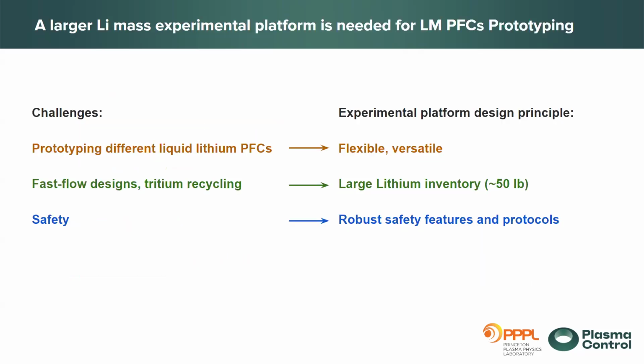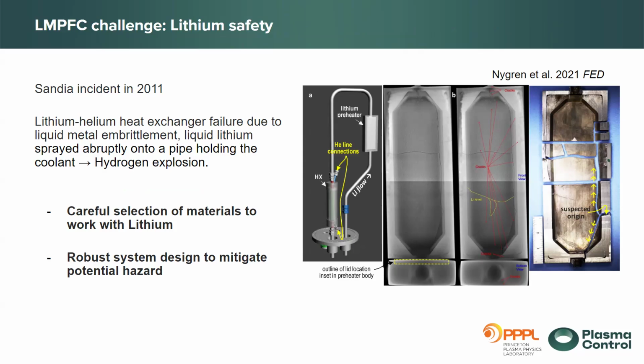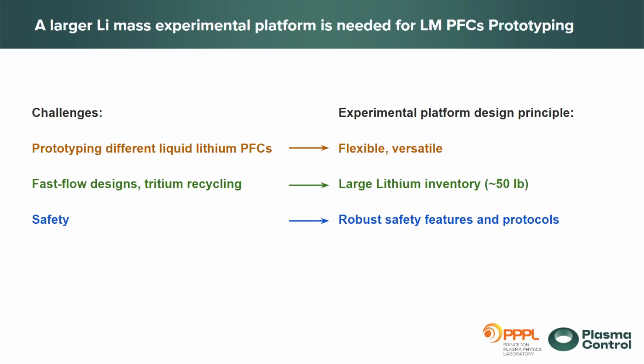Just one quick comment. The lithium actually sprayed onto a water-cooled ceramic break, and so that immediately cracked and let water into the system. It wasn't a metallic cooling pipe. So don't use ceramic. Anything porous that can trap moisture, don't use it.